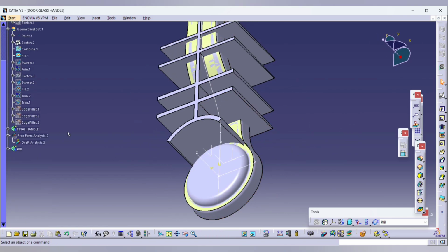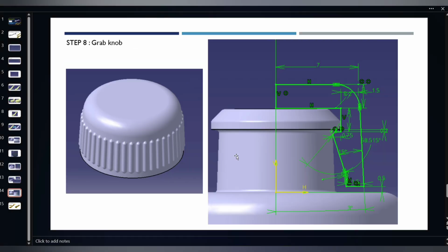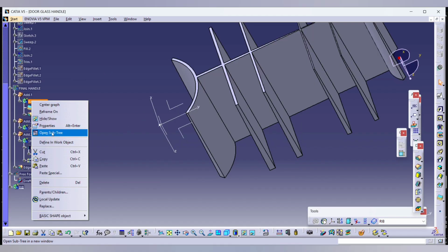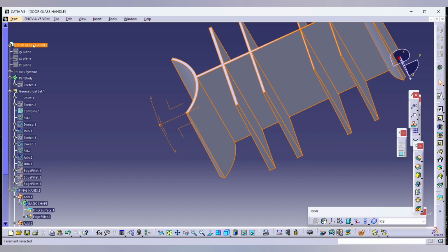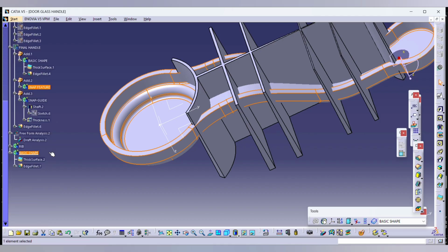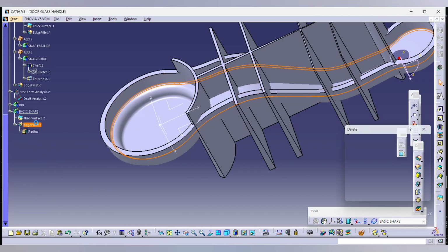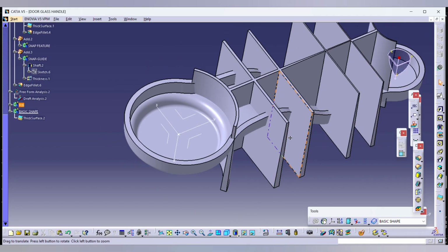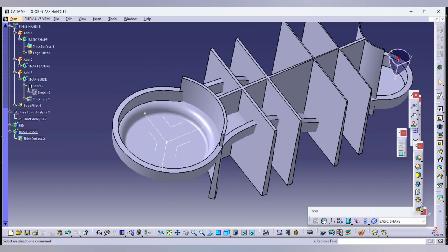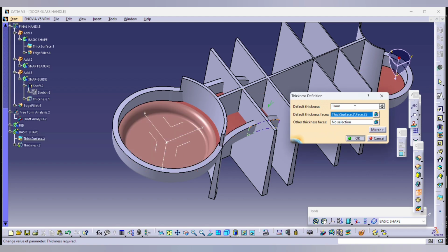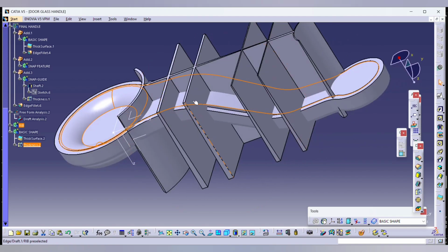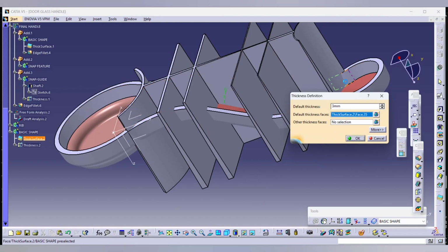So now further we'll move ahead for the intersect command in the boolean operation. So for intersect, just copy our base body and paste it directly. We'll delete this radius because we have to apply inner side thickness. So first of all we'll define the body, select the face, and apply the inner thickness as 4 mm. So 4 mm is too large, 3 mm.